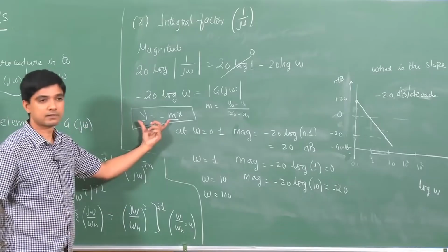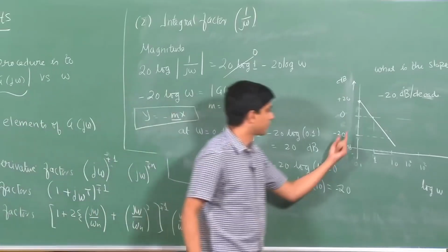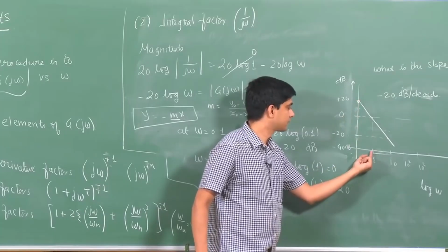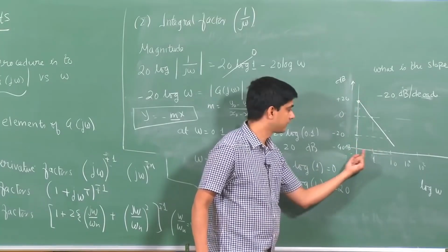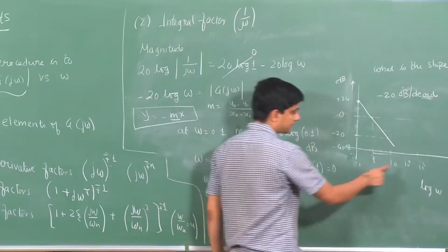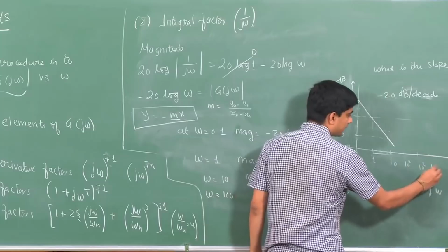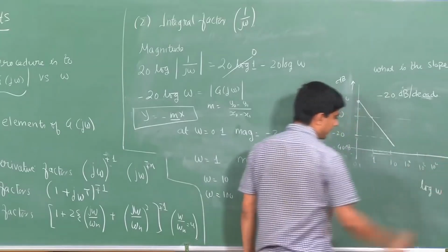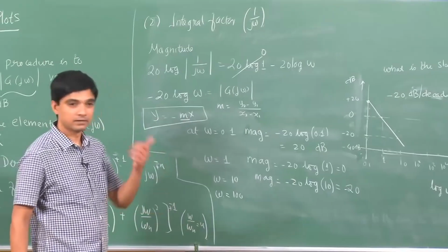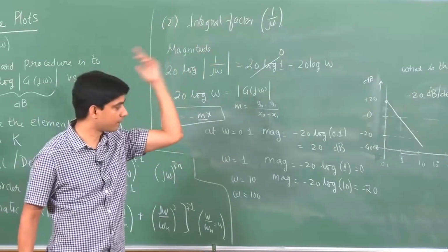Again, it is very similar to what is happening here: y2 minus y1, that is 20 decibels, over x2 minus x1, that is a decade. The advantage of doing this is that I will have 10 power 3, 10 power 4 and so on, and frequencies are usually from very low frequencies of 1 hertz till 10 power 3, 10 power 4.